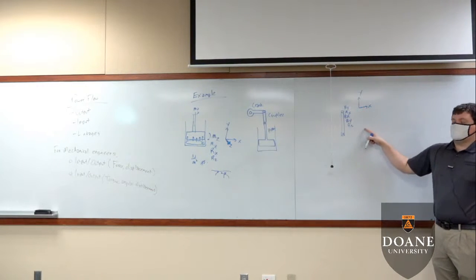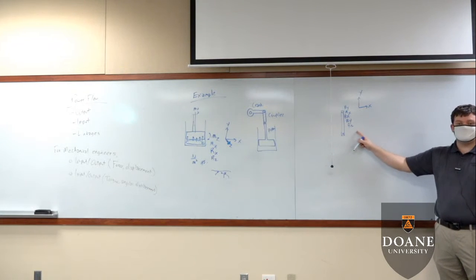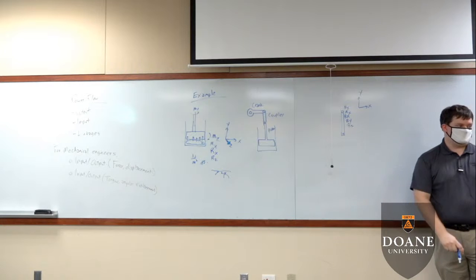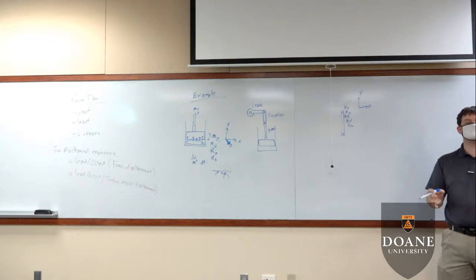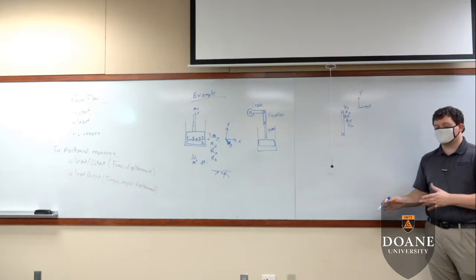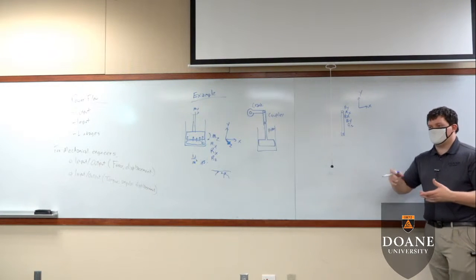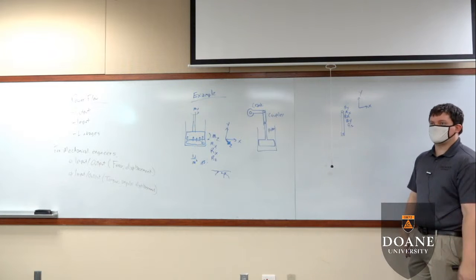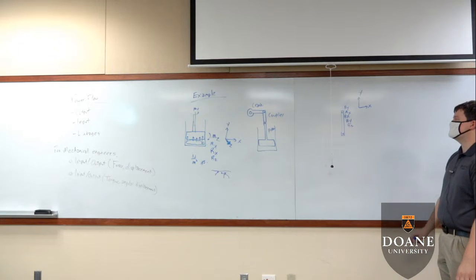All of these other elements are constrained. But I do not have an Mz value that's caused by this joint. Okay, there may be friction. Friction would create an Mz value, but it is not itself a boundary condition. Friction happens if you provide a moment large enough; the friction only serves as a power loss, not as a boundary constraint.